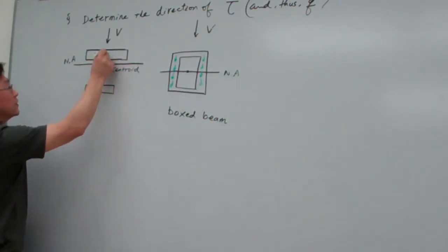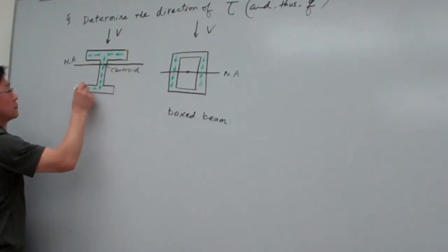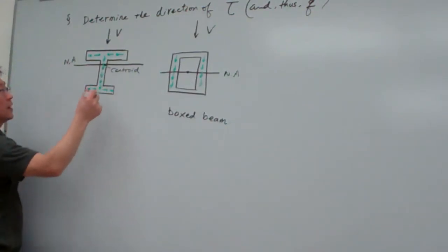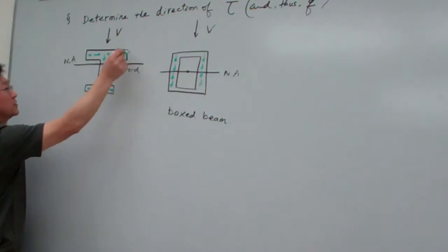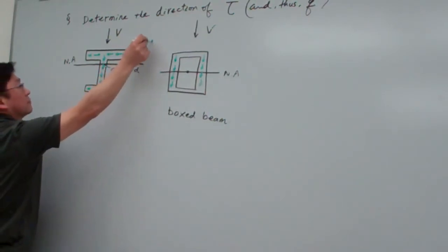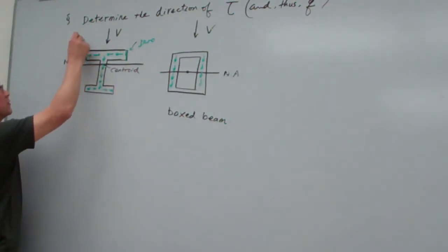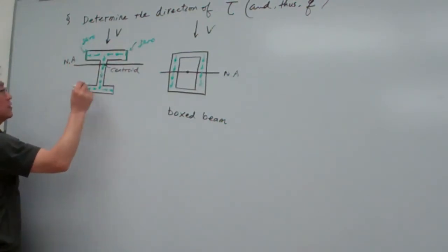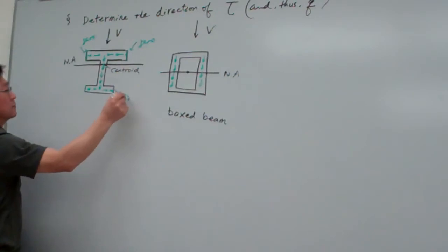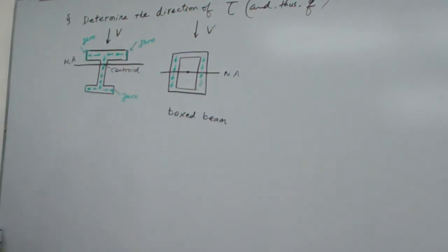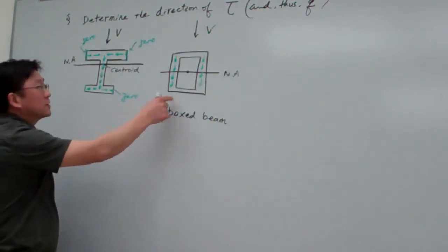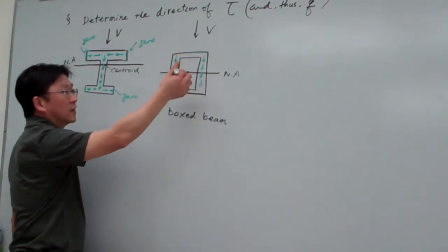So in this way, the shear will be like this. Starting from here, this side is 0. Basically, the shear stress on any free surface will be 0. Here is 0. For this case, again, we want to maintain the shear flow.